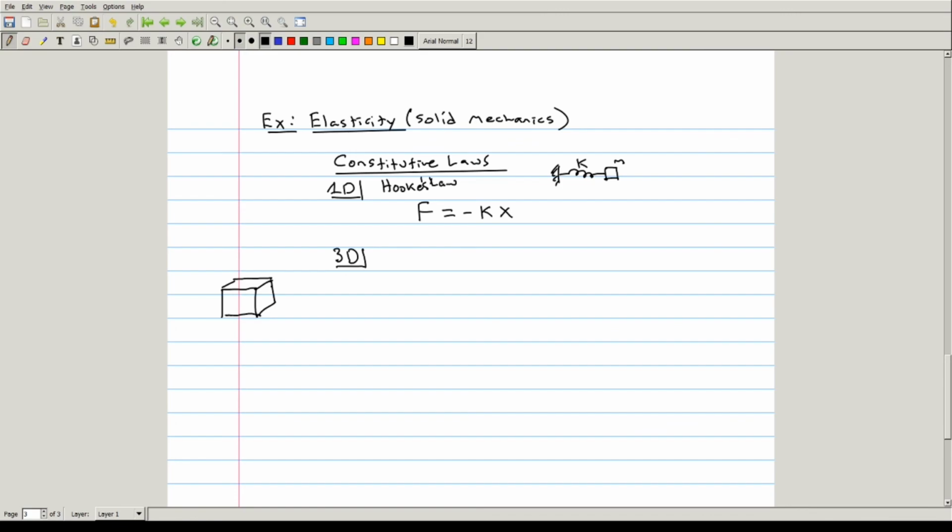At any given point inside the body, you have individual stresses or forces in each direction, and you also have torsional, or rotational, forces, as well as rotational stretches about any of the various axes of the body. So in order to correctly describe this in 3D, you have to consider what's called the stress tensor, typically noted as sigma.